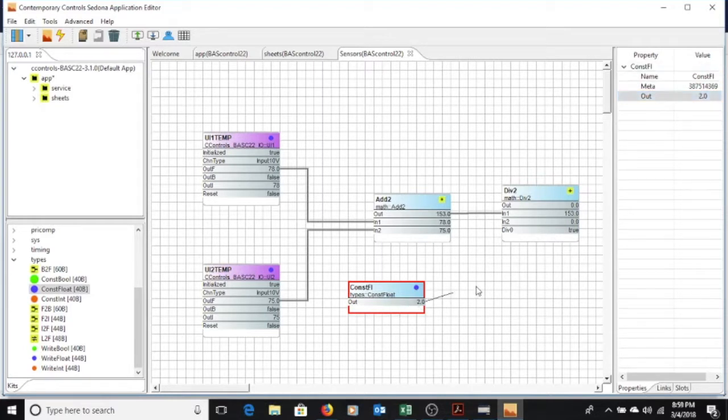If you're paying attention, obviously we're wiring this up to become a thermostat. But what I want you to see in this entire array here is that you can add stuff, you can divide stuff, and the float functionality is something that can help you overcome a hurdle, maybe of a complex function for either defrost timers or air handlers or other things. Just to show you, this is one application of the 1,000 you can do to actually make a control strategy.